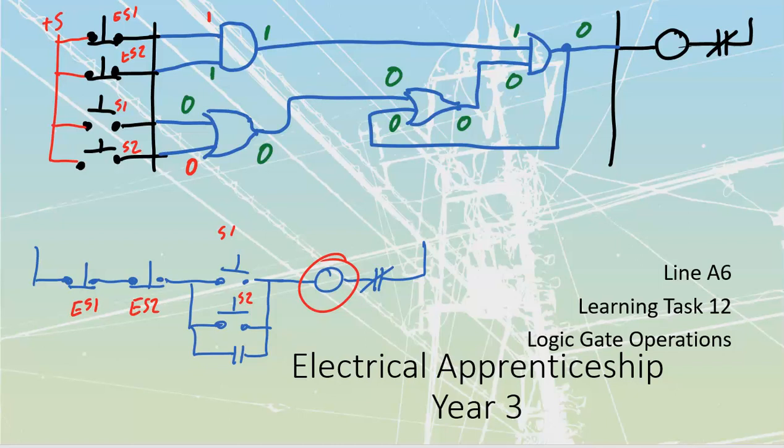These days, despite what anybody that you work with might try and tell you about the value of ladder logic, it is dying. Okay, I was just talking with somebody from ABB, they're a major manufacturer, the other day, about languages, and I talked about a month ago with somebody from Schneider as well, because these are areas of interest that we stay up to date on. At this point, function block is probably sitting at about 70% of the programming that goes into new installations, using ANDs and ORs. Ladder logic, rapidly losing ground.